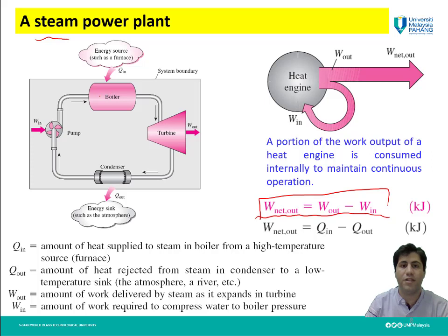Then we have water here. Due to this huge amount of thermal energy, the water is evaporated and we have high temperature steam here which is under high pressure. It will come to the turbine and cause rotation of the turbine due to its high pressure. Then the thermal energy of the steam will be converted to shaft work, the work of the shaft of the turbine. Then this steam will go to a condenser, which is the sink, and the extra heat will be released to the sink. And again, this process will happen.